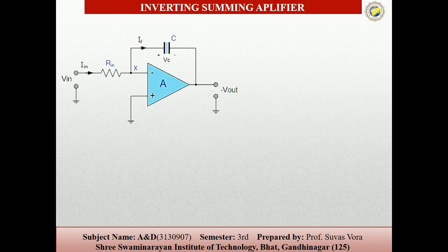Now we can talk about the integrator. If we talk about integrator circuits, you can see that the output is the integral of the input. You can see that G is the virtual ground and the input voltage Vi charges the capacitor to a voltage.